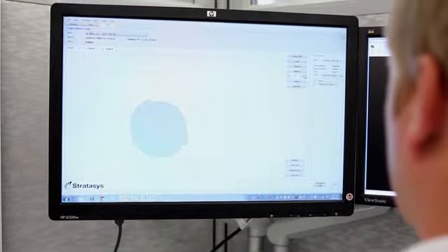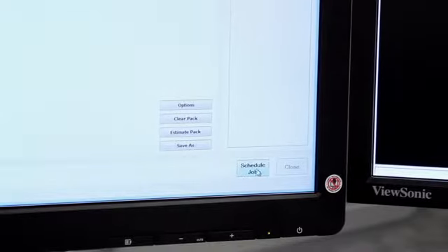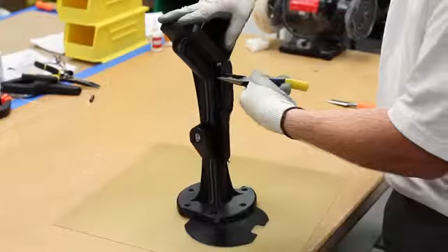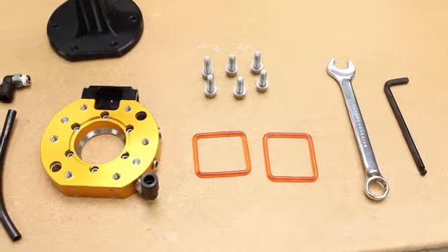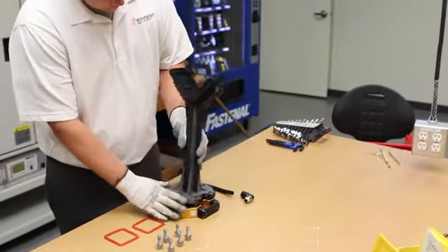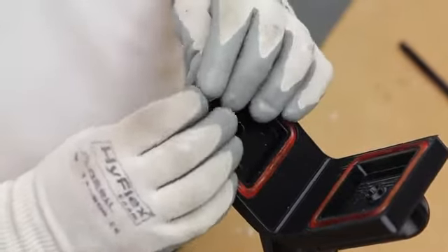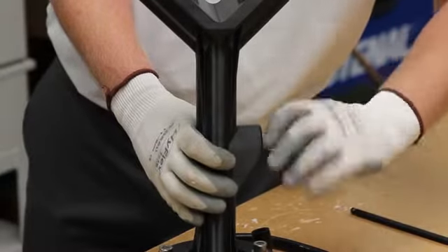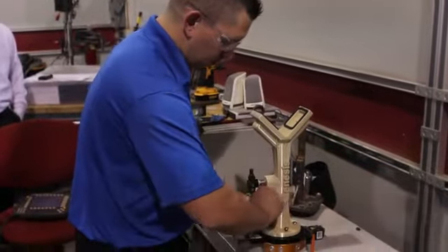Next, the file is uploaded to the FDM 3D printer, where the automated toolmaking process begins with the click of a button. Once the print job is complete, the part is removed from the build chamber and any sacrificial support material is dissolved or detached. Now the FDM parts can be fitted with all the supporting components required to make a functional tool. These may include fittings, tool changers, gaskets, sensors, paint guns, welders, mechanical or pneumatic fingers, and other components. The end-of-arm tool is now ready to be mounted to the robot so that it can do the task it was designed for.